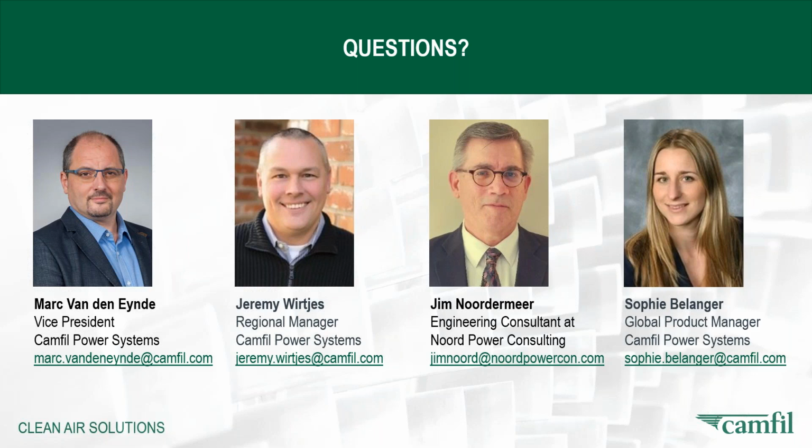That's a good question. Of course, E10 or HEPA filtration focuses on stopping the particulates, dust particles down to very submicron size. But when you talk about moisture and salt, especially to avoid hot corrosion, you really need to make sure that the media is also hydrophobic in the design of your filter construction. The filter element, as well as the filter house construction, is also completely airtight, bypass-free and seal-free. So you need to make sure that your filter construction is made in a way that whatever moisture gets into your filter is evacuated as soon as possible out of your system.